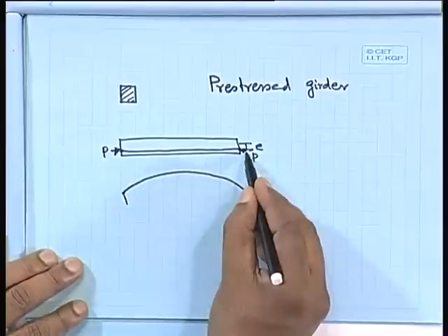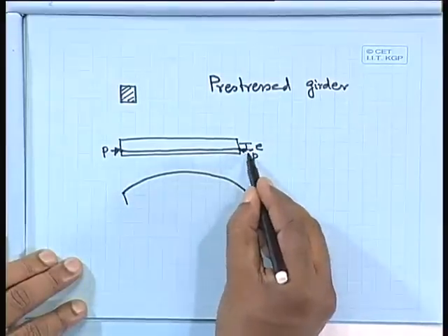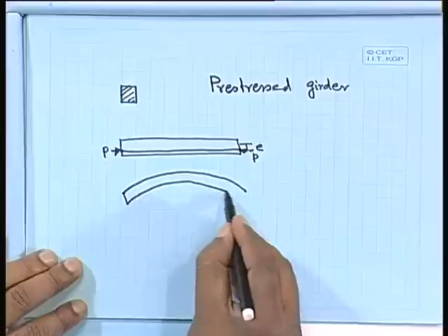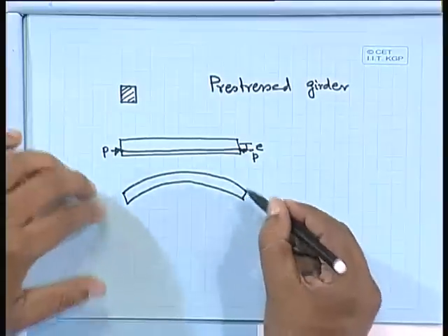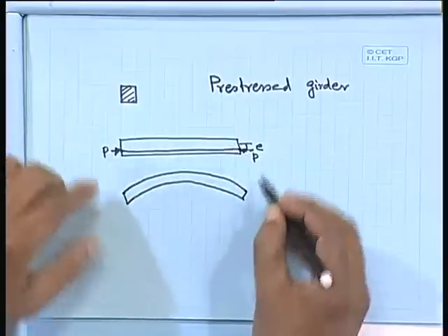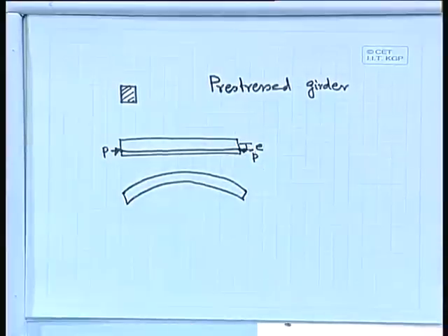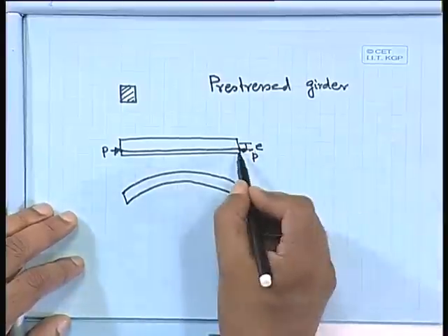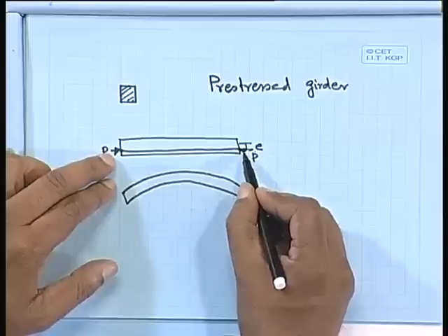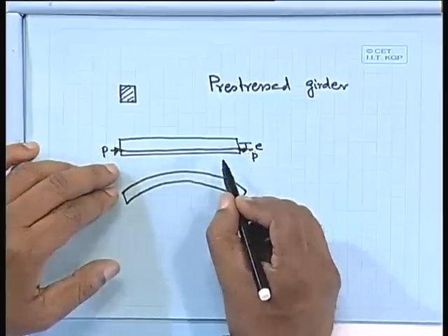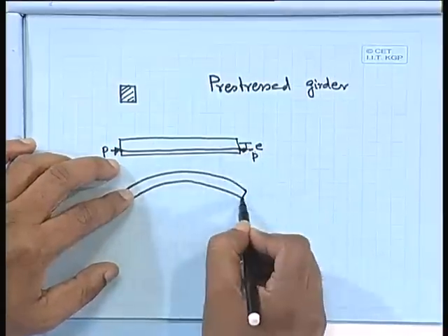Due to bending, due to the moment developed here, initially it will be like this. Not that much, but anyway it will try to bend in this fashion, because I am not putting the load in the center. Instead, I am intentionally applying it at a certain eccentricity. So it will develop a moment and also axial force. So what will happen? It will make like this.